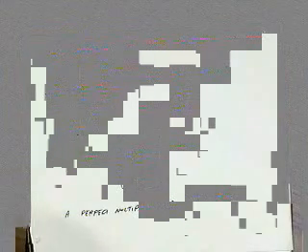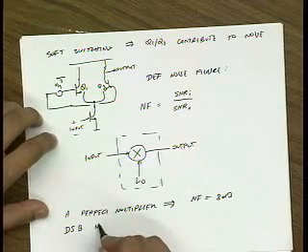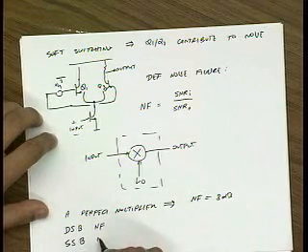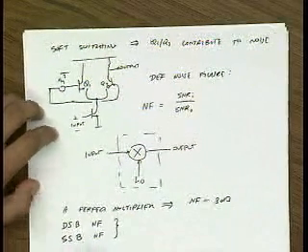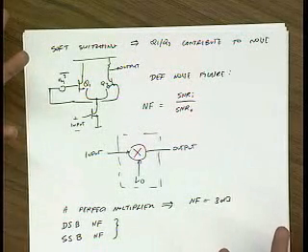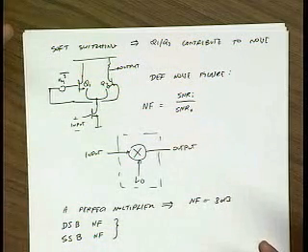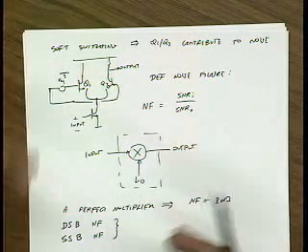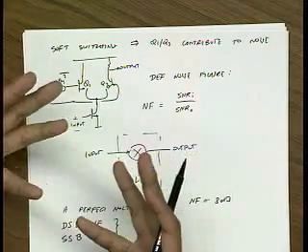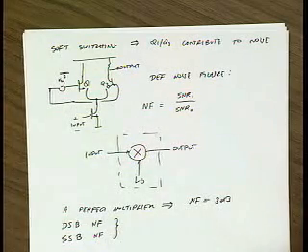There's also a complication because you have to take into account if there's modulation in the image band. So there's a double sideband noise figure and a single sideband noise figure. Okay? Double sideband noise figure assumes that you have actual energy in both sidebands. So there's modulation in the image band, in which case if you go through even a perfect multiplier, you get noise from the image band, but you also get signal from the image band. So the noise figure again would be 0 dB.